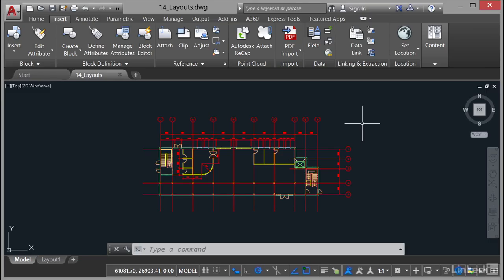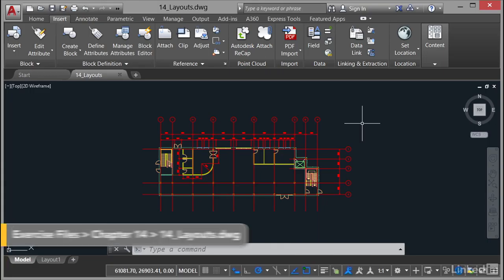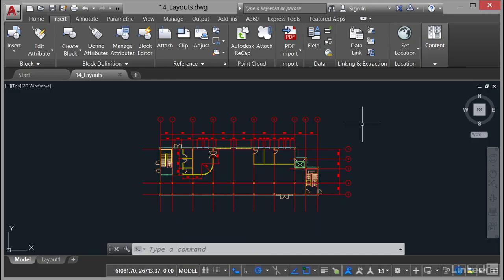We're now in a new section of our AutoCAD 2017 Essentials course. What we're going to be looking at is creating layouts and their associated annotation. So we're talking about things like title blocks and scaled viewports, basically in an effort to communicate our design intent with AutoCAD itself. Now what we want to do is show information from the Model tab in a Layout tab. So we're going to create a new layout and then add a viewport to a particular scale to that layout.